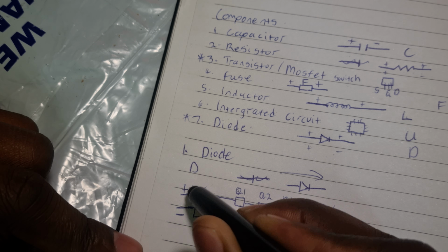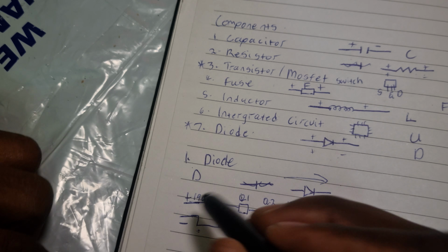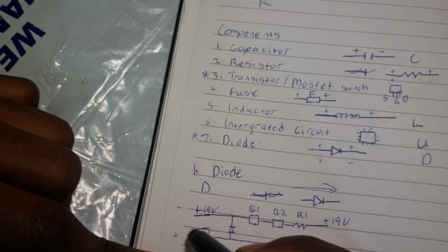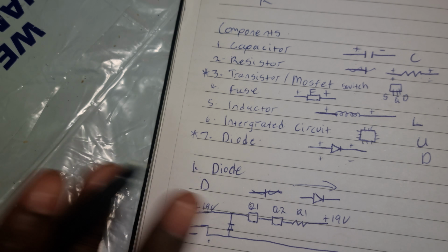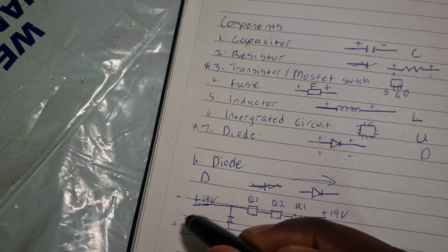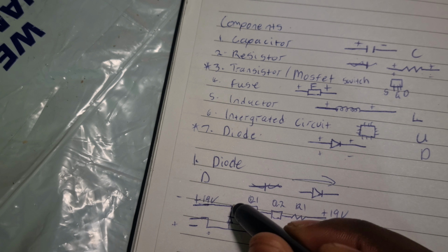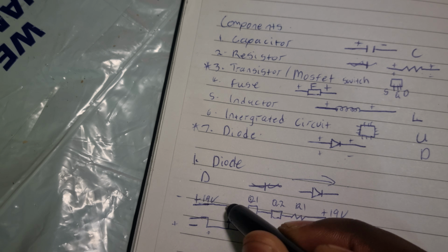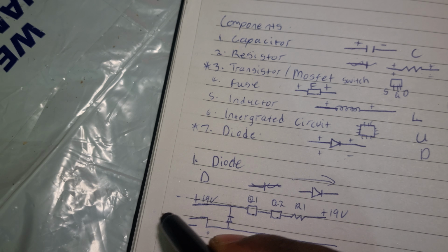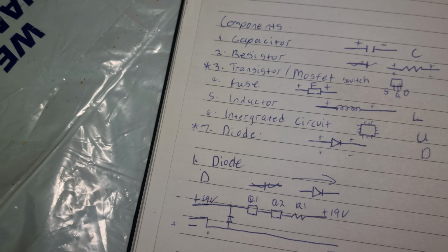But if you put your charger in reverse and you've got your positive this side instead of that side, by design it will just go through the diode and short out with the negative of the charger. So you can see now your positive is here and your negative is here. Instead of going all the way through and burning stuff in the circuit, it will just immediately, as you plug it in, go in reverse through this diode and short out. So your charger is the one that shorts out. It's cheaper to replace a charger than to replace an entire laptop.